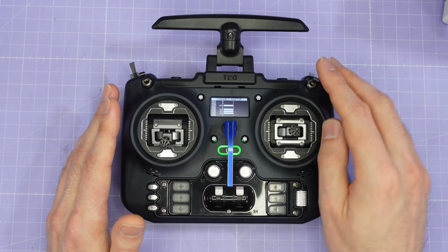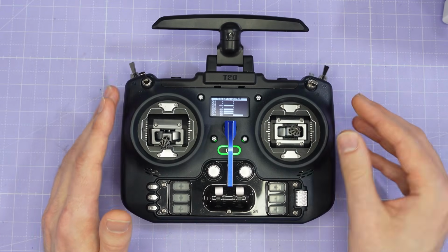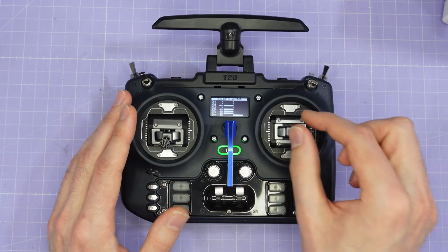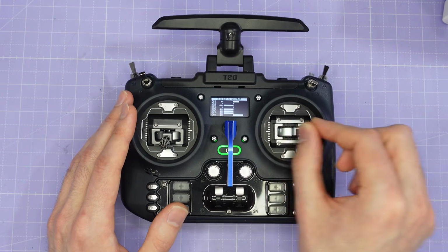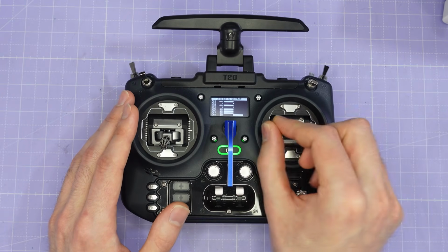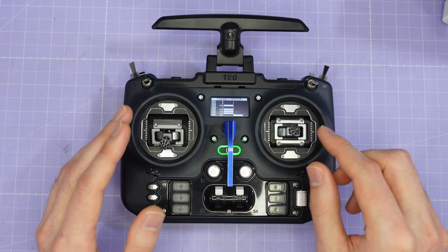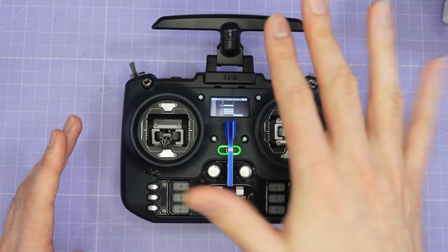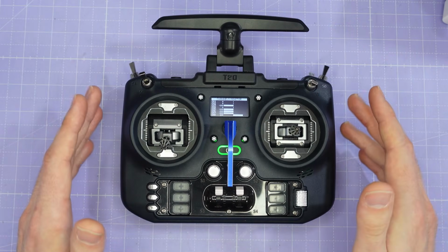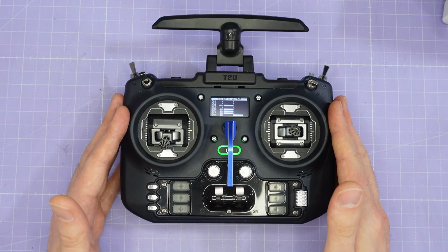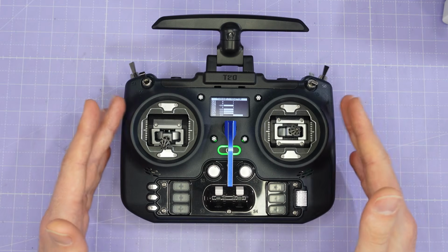The second is consider tuning in angle mode. Tuning in angle mode is a lot easier because when you do wobbles like this left to right, you actually get really sharp inputs to the PID controller, and the quad is sort of just wobbling in midair, and that's nice and easy to control. So I would definitely recommend doing most of your PID tuning in angle mode.